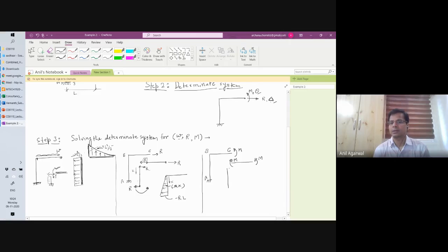You have to have a member connected to that end, which will provide that support or boundary condition. We do have a member AB connected to member BC at B. That means member AB is supplying that moment, which also means from Newton's third law that member BC must be applying an equal and opposite moment on member AB.